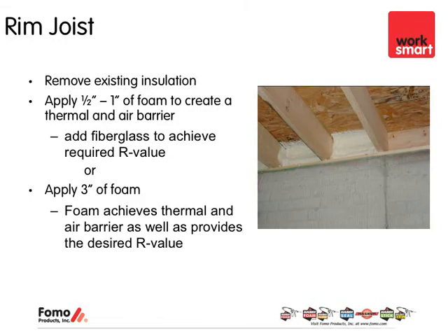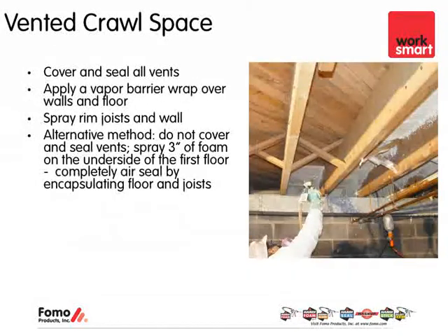We're now going to talk a little bit about a vented crawl space. A vented crawl space can create some problematic areas, typically in that one picture that we showed, if the venting is not working properly, meaning that the moisture entering the crawl space is not properly being exited from the crawl space. In the picture that we showed, the moisture was then condensing on the underside of the first floor, and it created mold and mildew issues.